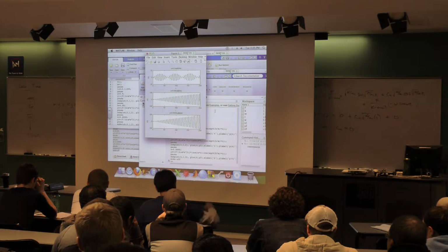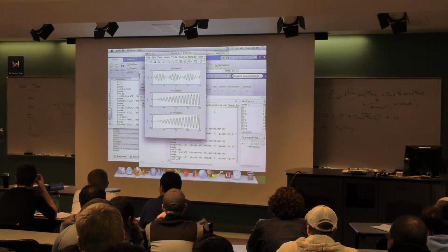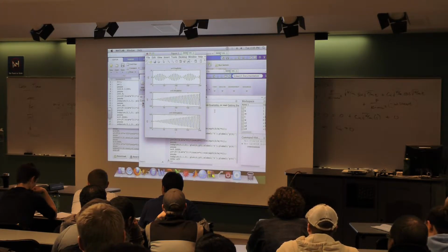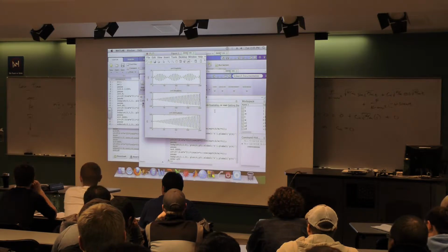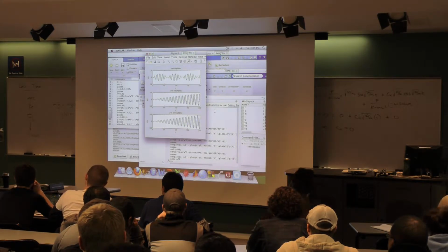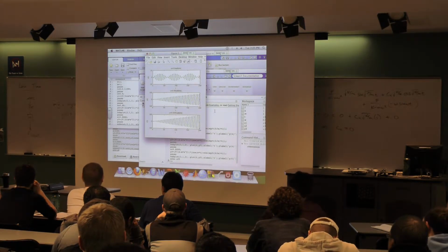And so if the tire wants to bounce around at a certain frequency based on its imbalance, the speed of the tire is forcing it to vibrate the way that it would want to vibrate on its own. So if you speed up, you change the frequency, and all of a sudden my beater car drives nicer at 65 than it does at 55, okay? Or if you slow down, 45 instead of 55.